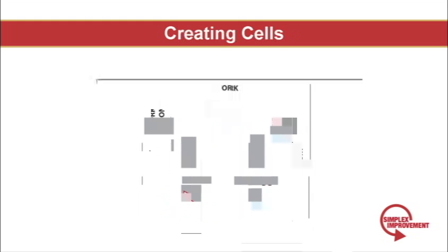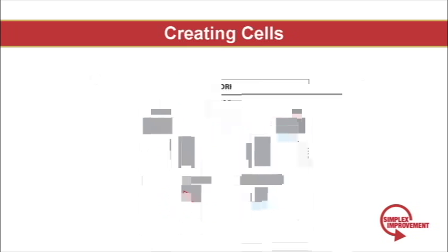Your other option is to have a mixed model cell. In both of these cells, red and blue pieces are being produced. An advantage of this is if one worker happens to be absent, you can still get both product types produced. This model is actually more disciplined because it forces you to reduce setup times and think in terms of leveling and cross-training. So long term, this model has an advantage over the dedicated cell model. Again, both types have their merits, so carefully consider how you want to run your cell.